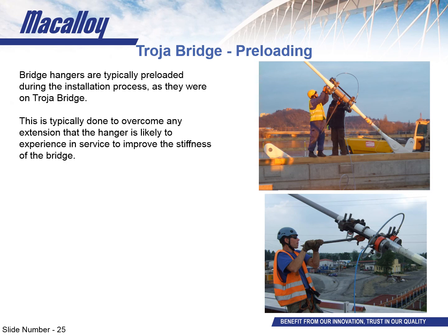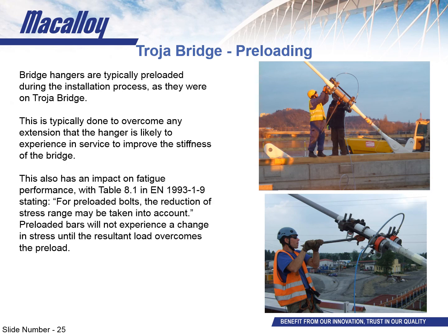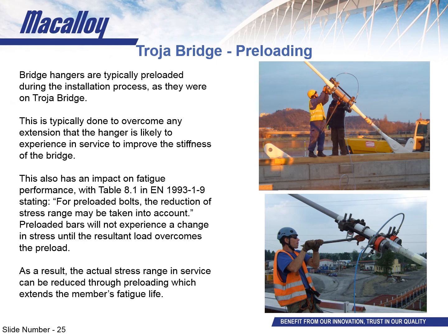This is also very relevant in a fatigue application, as in Table 8.1 in EN 1993 Part 1-9, it is stated that for preloaded bolts, the reduction of stress range may be taken into account. Now, preloaded bars are already under stress, and this stress will not change unless the force in the member has been overcome or a secondary source of load, such as a bending moment, is applied. As a result of this, the actual stress range while in service can be minimized through preloading, and this significantly reduces the fatigue demands on the system.